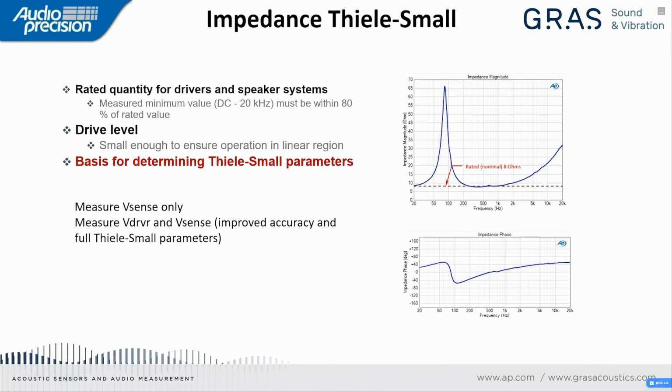You can see we have an impedance phase response at the bottom right of the screen, and impedance magnitude, where you can see the resonant frequency of the drive unit, which is the peak in that response.